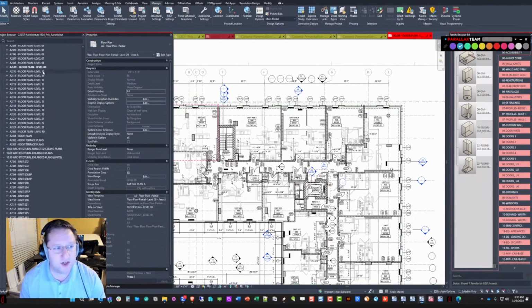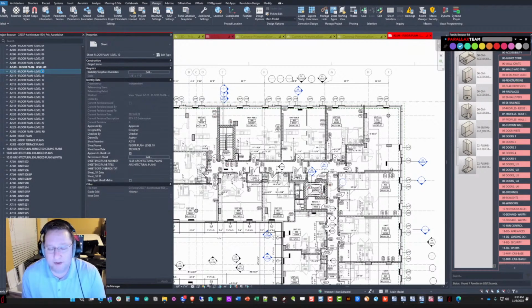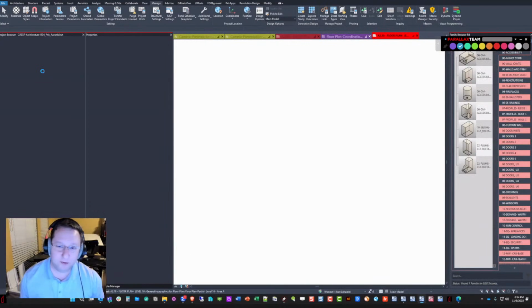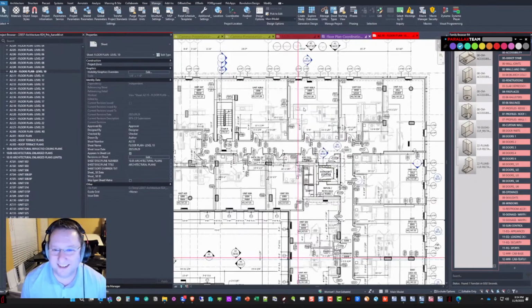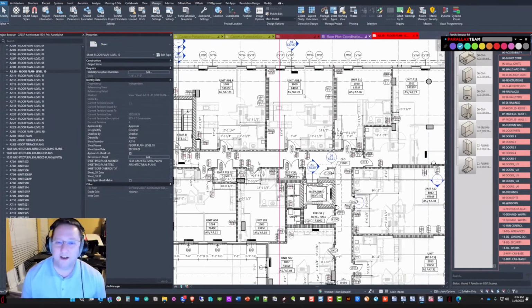So just to check, I'm going to go up to level 10, unless I unluckily picked the wrong group, the same group should be there on level 10. Right, and the wall will be dark instead of halftone, ideally, right? So that's how you'd be able to tell. If it propagated, it'll be dark. I'm betting it's going to be light. But if I'm wrong, come by booth 355 next week, and I'll get you a free drink. Yep. So it's still light. Got it. So when they're set to vary by group instance, they do not propagate changes. Which is fine.